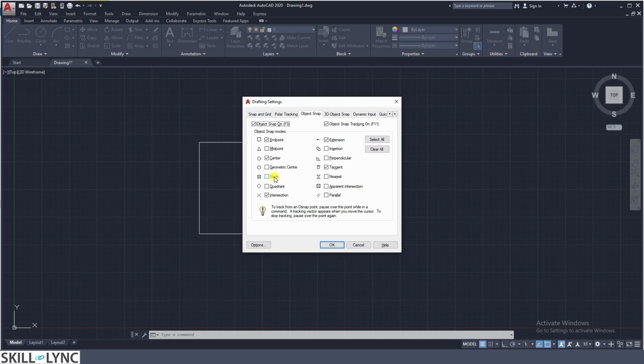The next command, the node, is useful when you are tracking to a dimension text object or a point object. With that, you can define the object by nodes and hence track it to those nodes, because these will be hidden. For a text box, this will denote the boundary of the text box. That is typically hidden because you are looking only at the text dimensions. So this will help us to position the text box in such a way that the objects are aligned.